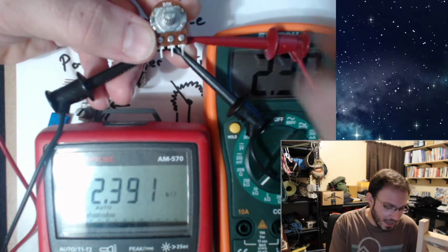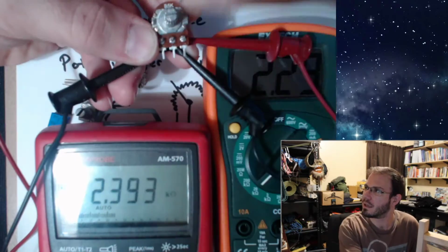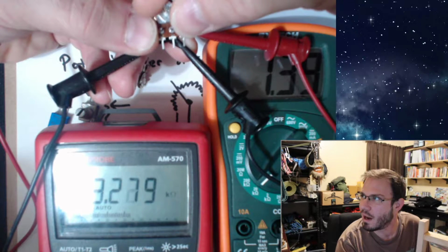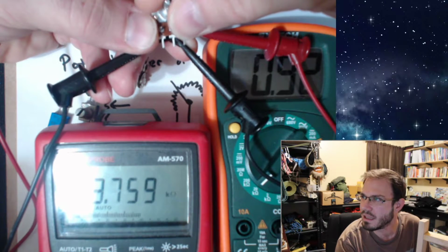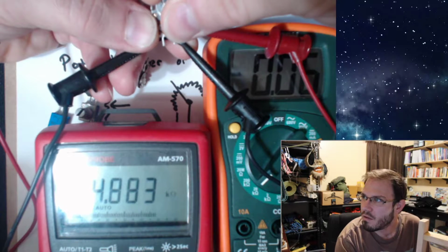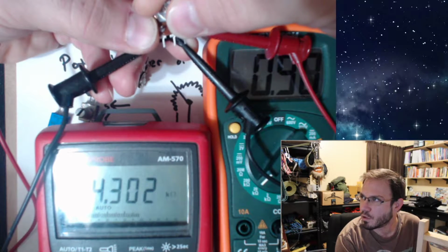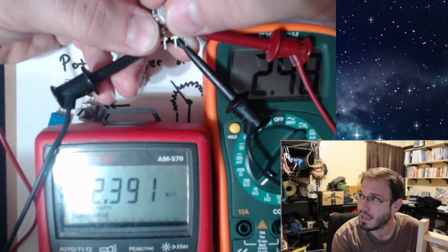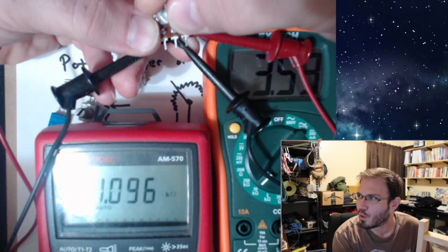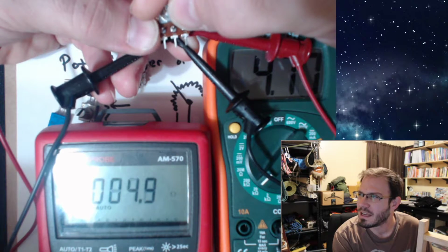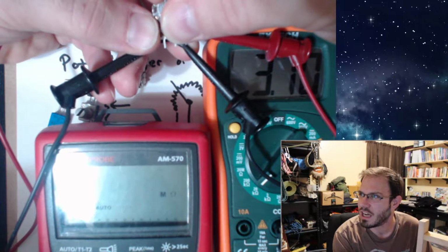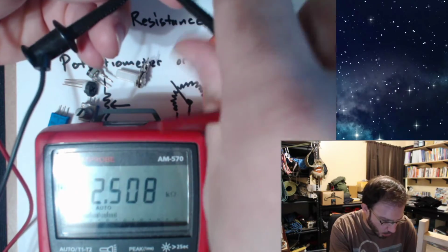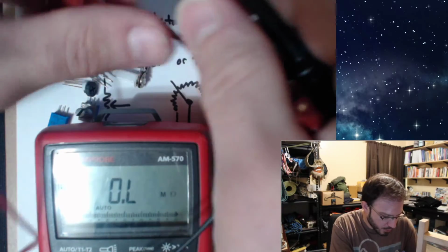And then as I crank that to the right, okay, now you can see the resistance on the right multimeter is going down while the resistance on the left multimeter is going up. So very clever and useful arrangement. Whenever you have a volume knob for something, you'll see this becomes very valuable to have a changing resistance. Okay. Now that's one type of variable resistor.